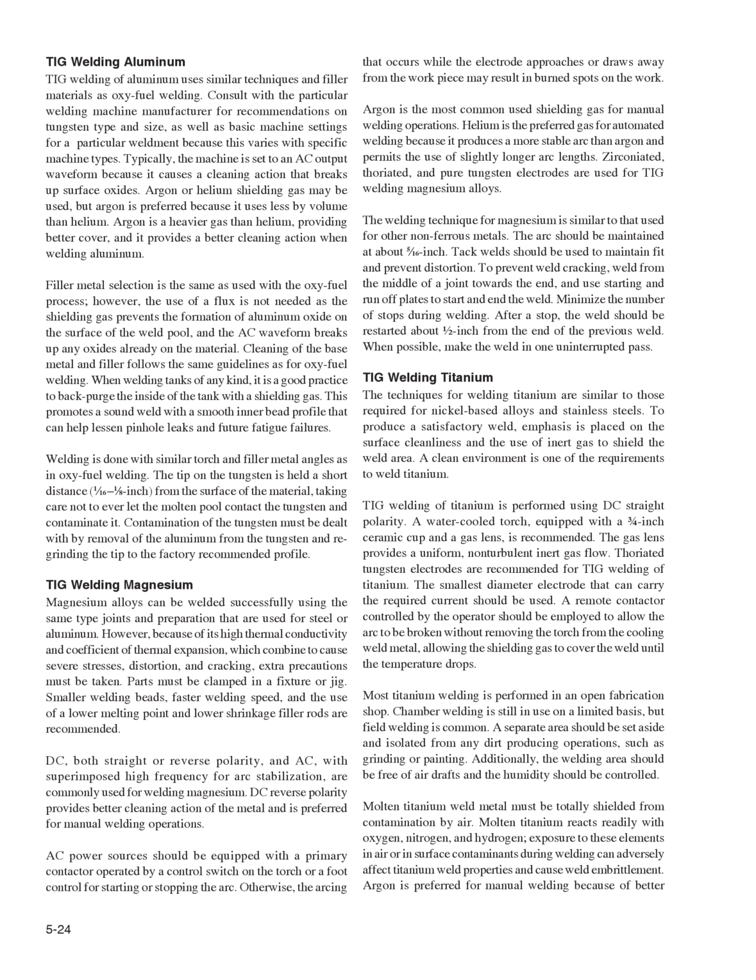Cleaning of the base metal and filler follows the same guidelines as for oxy-fuel welding. When welding tanks of any kind, it is a good practice to back purge the inside of the tank with a shielding gas. This promotes a sound weld with a smooth inner bead profile that can help lessen pinhole leaks and future fatigue failures. Welding is done with similar torch and filler metal angles as in oxy-fuel welding.